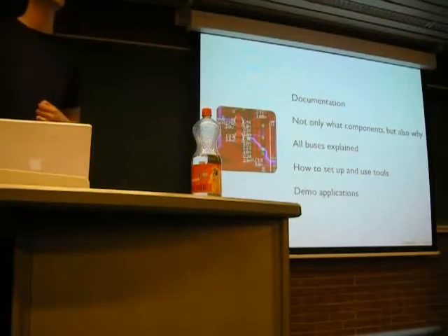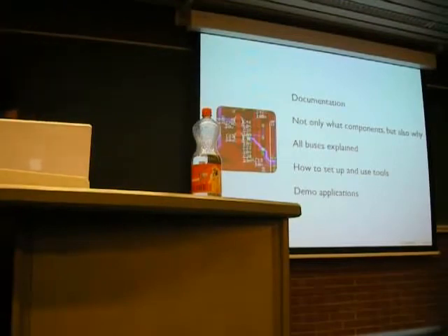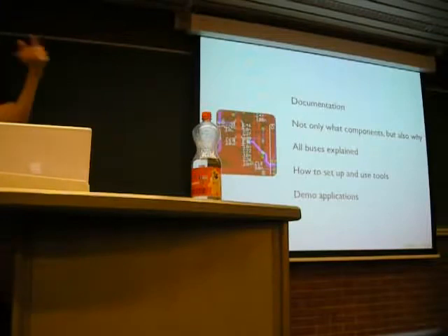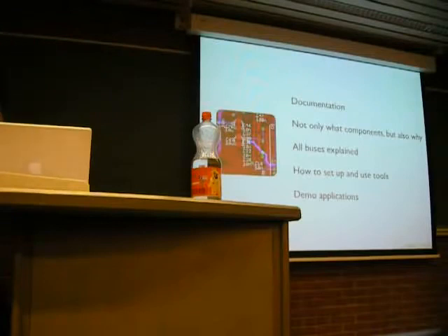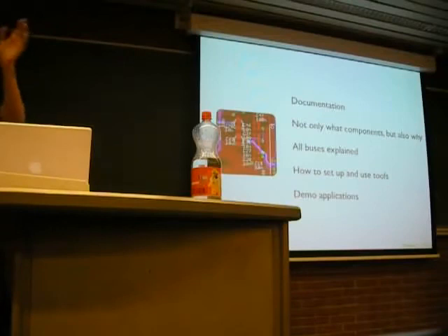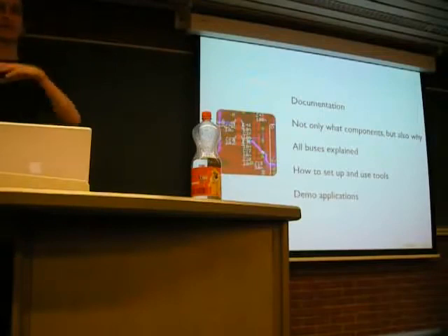No, I didn't, unfortunately. I spent about a week trying to get it working, and then in a few days I programmed my own tool. Because OpenOCD thinks it's smart, it tries to align the bits for the proper chip. There are 3 chips in the bus. And the Xilinx tools also try to be smart, so they also align, and then of course it doesn't match up. Disabling that turned out to be quite tricky. We just skipped that and figured I'd write my own tool and get something working.